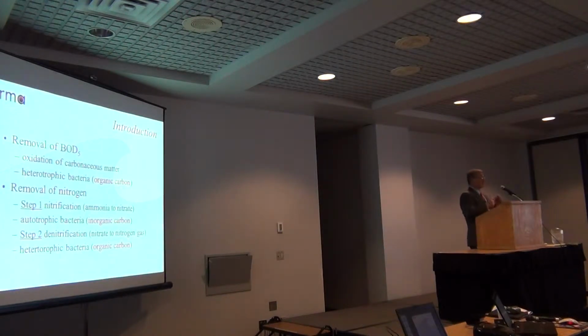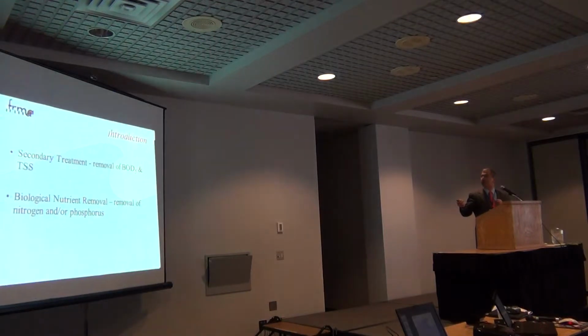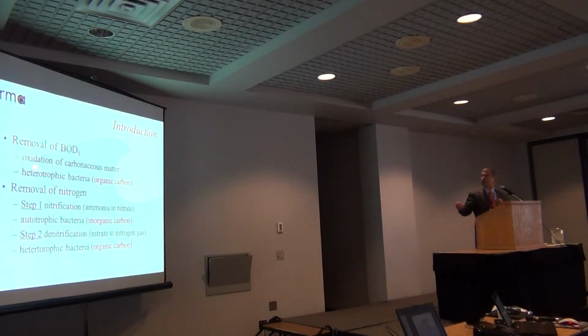Those bacteria are the same as the first group. Heterotrophic bacteria. Essentially, a large portion of the bacteria that can break down BOD can also, if you take their oxygen away, breathe with nitrate, and in so doing convert nitrate to nitrogen gas.